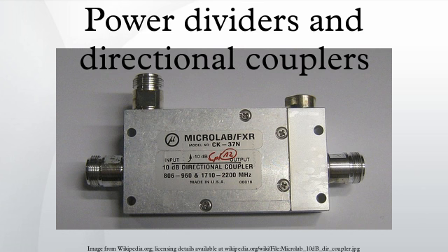Multiple output dividers. A typical power divider is shown in Figure 13. Ideally, input power would be divided equally between the output ports. Dividers are made up of multiple couplers and, like couplers, may be reversed and used as multiplexers.